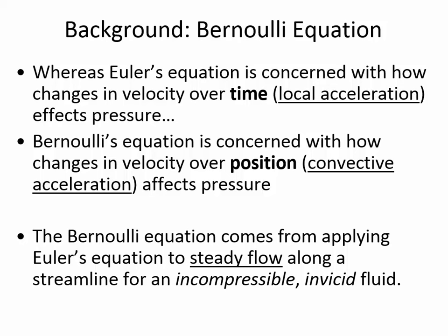So Bernoulli's equation, there are some circumstances where it does a pretty good job, and then there's some circumstances where if you're trying to use Bernoulli's equation, you're going to have a huge error. For example, if point 1 and point 2 are very far apart, then you're going to get a lot of error trying to model what's happening with Bernoulli's equation, because there will be a lot of energy loss, because the inviscid assumption is not valid, and the further apart 2 points are, the more we're going to feel it that we're not honoring the inviscid requirement.